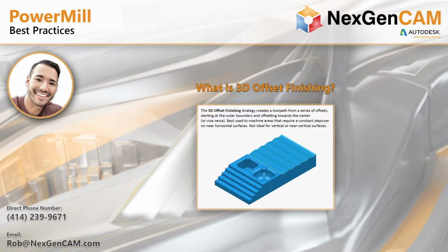3D offset finishing. I did not mention 3D offset finishing earlier, but there's a reason why I'm bringing this up, because a different toolpath actually utilizes 3D offset finishing. 3D offset finishing creates a toolpath from a series of offsets starting at the outer boundary and offsetting towards the center, or vice versa. You can start from inside out or outside in.